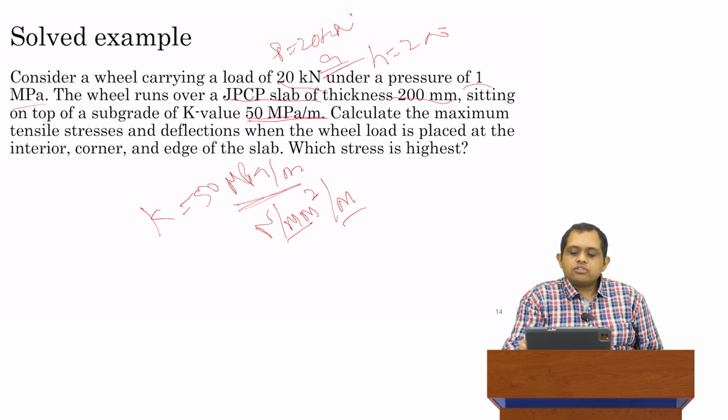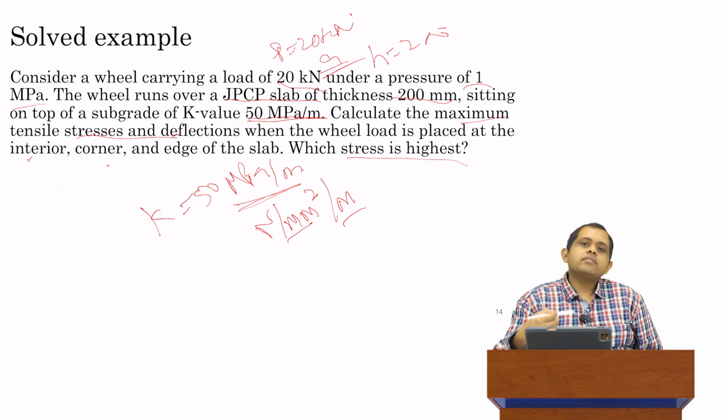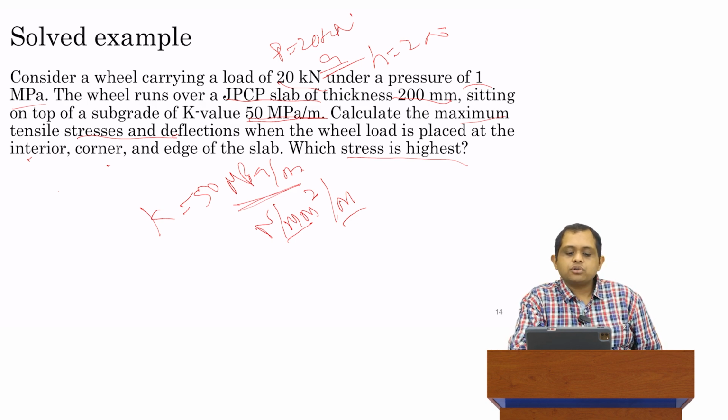Okay, the question is: calculate the maximum tensile stresses and deflections when the load is placed at interior, corner, and edge. And then among these three, calculate which stress is the highest. So basically, we are asked to go through Westergaard solutions and comment on the relative magnitude of the three stresses which we'll calculate out of it.